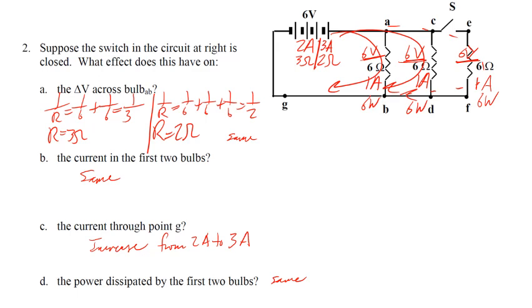However, notice that when we connect the new resistor, what changes is the total resistance is now 2 ohms instead of 3. We have lowered the resistance, which means we increased the current. That's good because we need that current to go through our third resistor. So all 3 of them will have 6 volts because they're in parallel, and all 3 are going to have 1 amp each because we've split up the current among the third one. But that also means that the power is going to stay the same for the first 2 light bulbs.